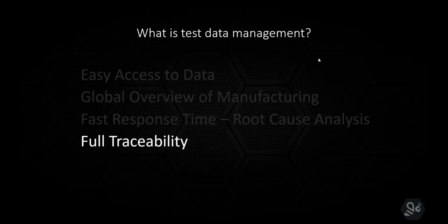The traceability system allows you to find both top-level modules and low-level subunits by using either serial number, so either the top level or the subunit information. So an example could be that you scan a module, you get all the test results for that product, but you can see that this top level unit has had a PCBA that has been replaced because you have 2 units being tested as part of it.